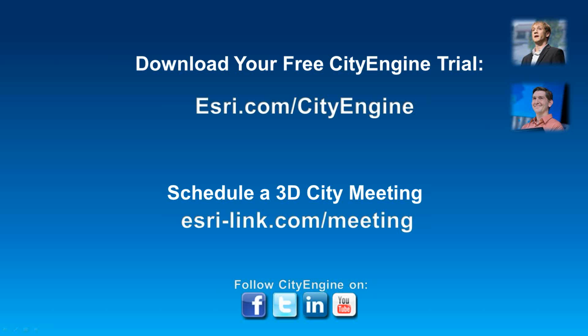CityEngine itself will allow for a little bit more complexity to your three-dimensional model, including, say, the facades of your buildings. But if you're a regular GIS person who's used to working within that ArcScene environment, we have a geoprocessing tool that you can just search for there and find CityEngine, to convert from an ArcScene document to CityEngine itself. So once you've got what's called a 3DS file in this case, you can upload it to your ArcGIS Online account, and then choose to share that internally or externally.